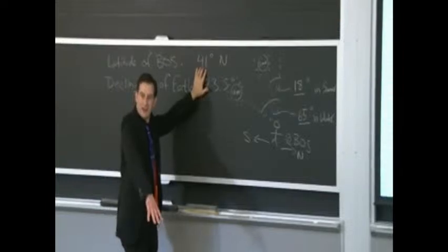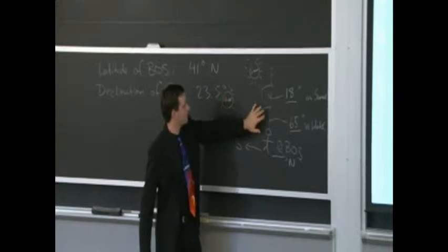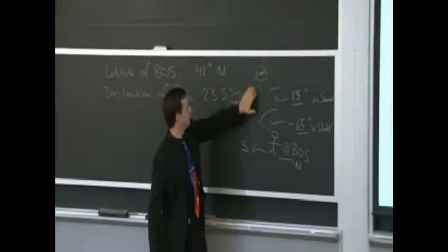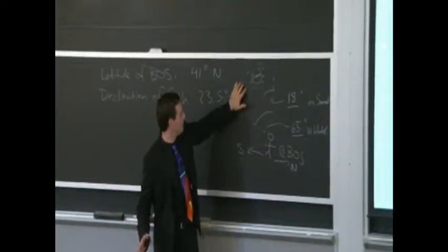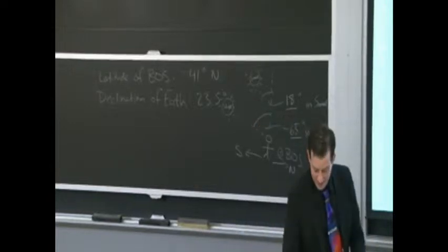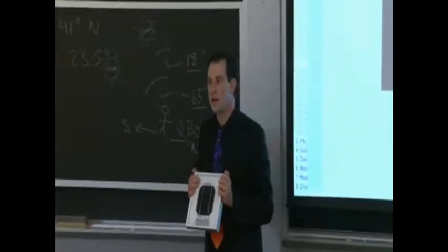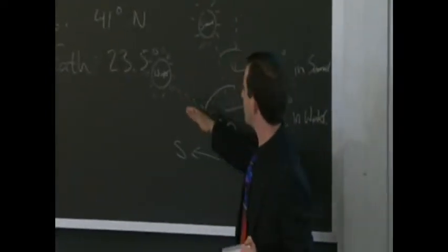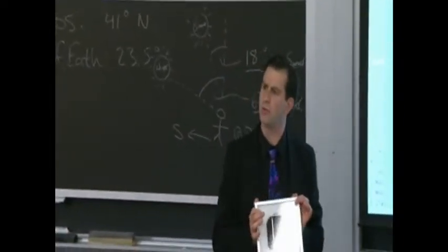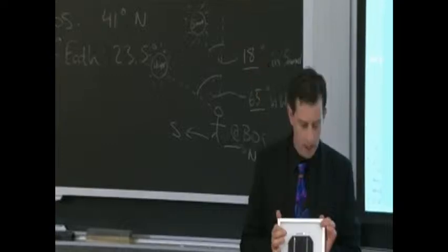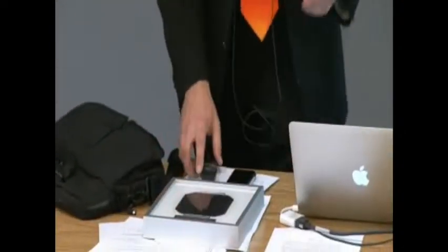So if I point my panel at latitude tilt, right? Since this angle was 41 plus 23, and this angle was 41 minus 23, so this one would be right around 41 latitude. So if I aim my solar panels at latitude tilt, then I'm going to get, on average, some pretty decent power throughout the year. I'll have a little less in winter, a little more in summer, just because of the amount of solar resources available. But all in all, I'll be all right. At most, I'll be off by 23.5 degrees. You can do that, and that's called fixed latitude tilt.